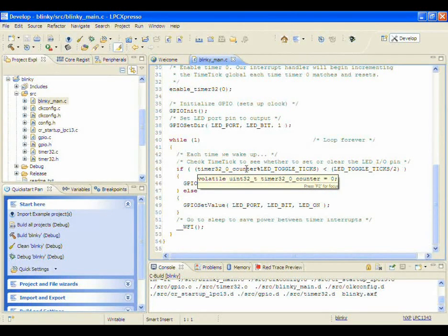This variable is in timer32.c, and this project has not been compiled yet. Nevertheless, LPCXpresso has already built a database of all of the variables and functions. This information updates in real time each time files are modified, so it remains useful even if you are in the middle of a big rewrite and you haven't been able to completely compile your code for several days.